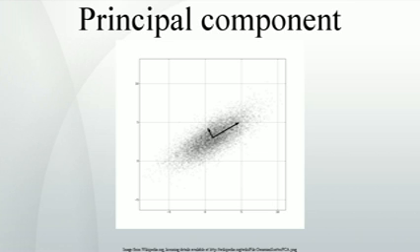In particular, Linsker showed that if s is Gaussian and n is Gaussian noise with a covariance matrix proportional to the identity matrix, the PCA maximizes the mutual information I(y; s) between the desired information s and the dimensionality-reduced output y. If the noise is still Gaussian and has a covariance matrix proportional to the identity matrix, that is, the components of the vector n are IID, but the information-bearing signal is non-Gaussian, which is a common scenario, PCA at least minimizes an upper bound on the information loss, which is defined as I(x; s) − I(y; s).